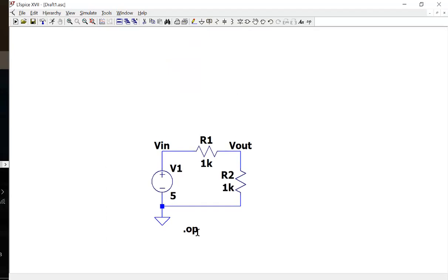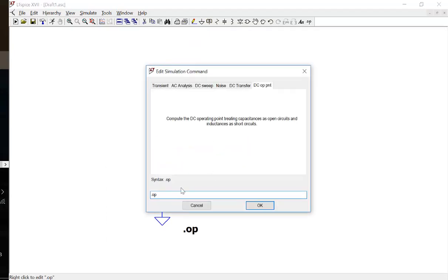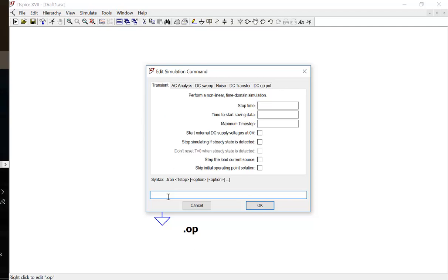Okay, and you can do another type of simulation. I want to see a waveform, like you probe your circuit using an oscilloscope. And it's a time domain plot, because on an oscilloscope, the x-axis is time, and the y is voltage. So I can delete it. Then I'm going to run the transient analysis. It's .tran, and you can run from 0 seconds to like 1 second. And the resolution for each point is, for example, 1m, which is 1 millisecond for each dot in the plot.